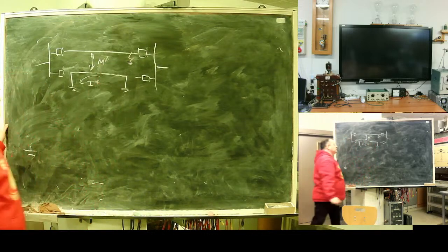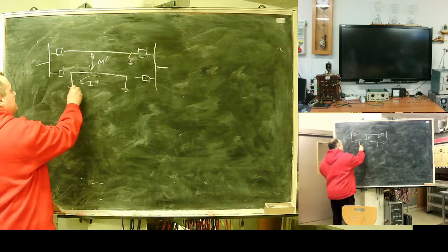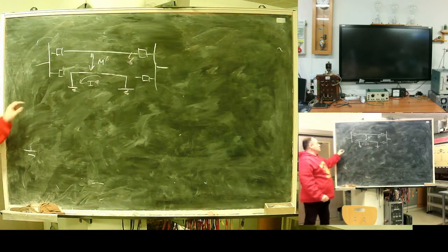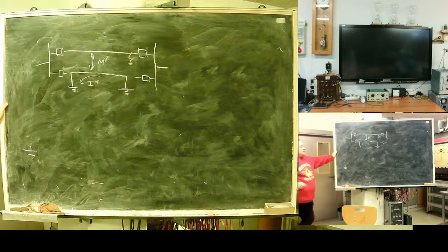This mutual inductance is real, accountable in zero sequence schematic. Current will circulate in the disconnected and grounded line. You switch the second line off for repair, but in case of fault there will be a current.